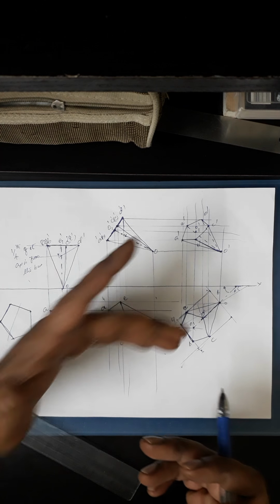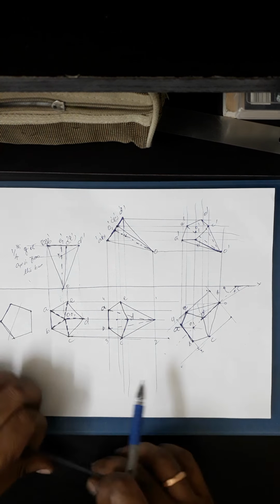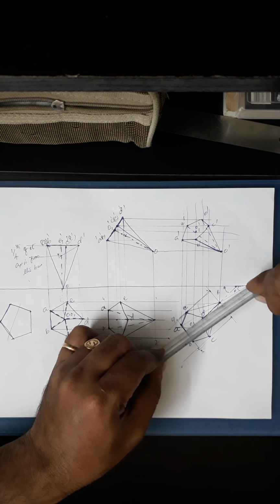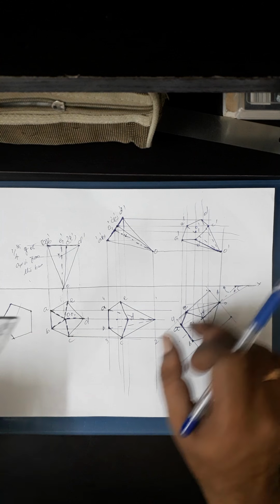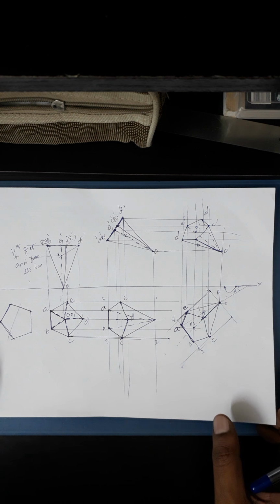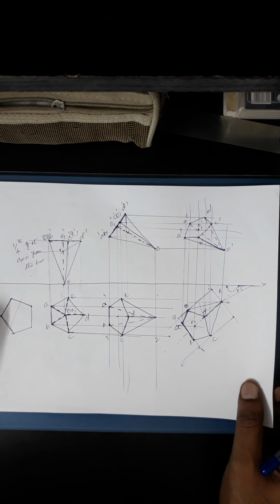The plane containing the axis and the edge, the topmost edge OD, is nothing but this, right? Okay, so that is inclined. Incline that with that given inclination. So same 30 degrees, you can redraw this view, get your final view. The same procedure for any pyramid if it is freely suspended.